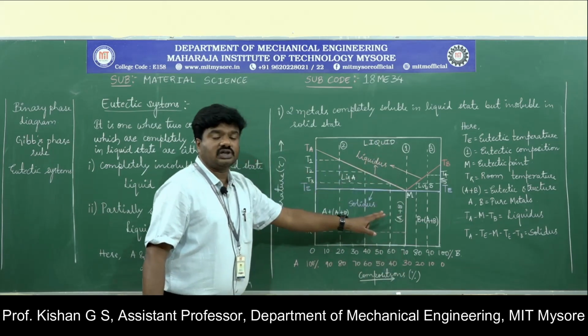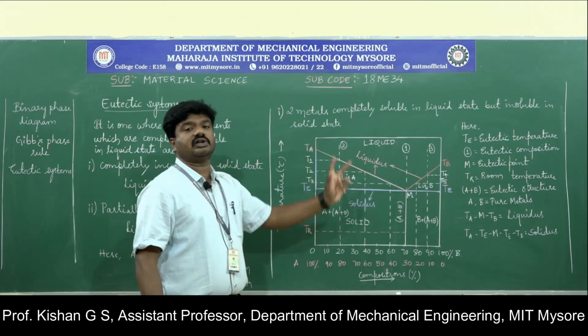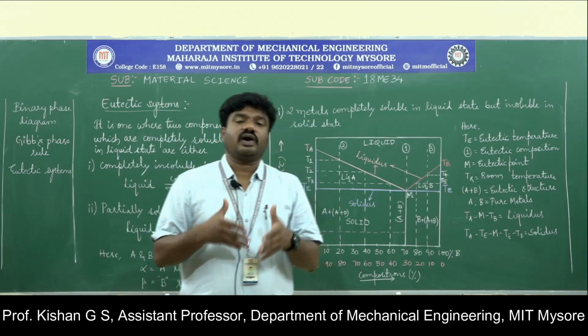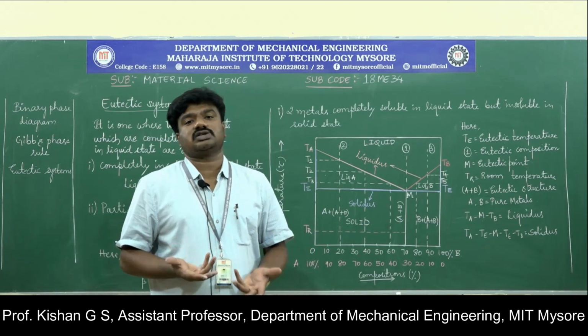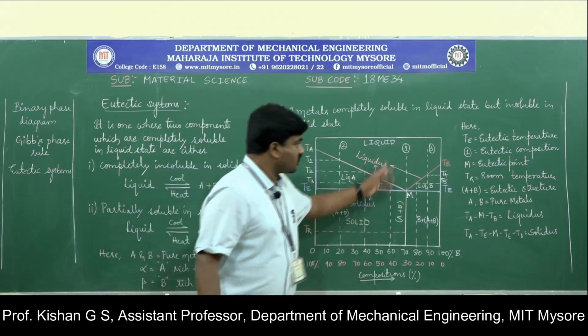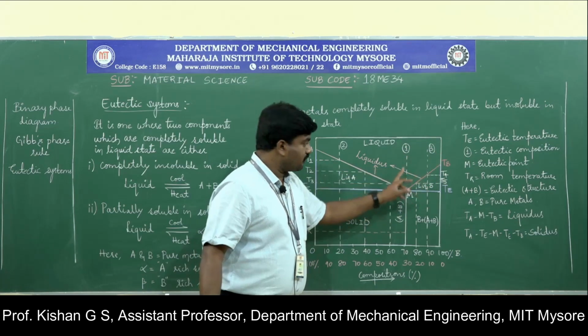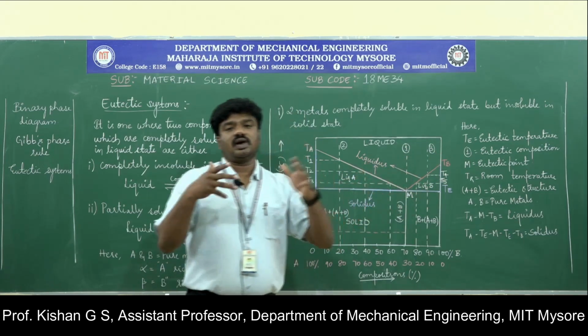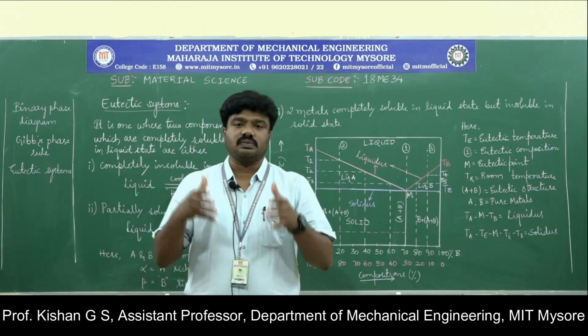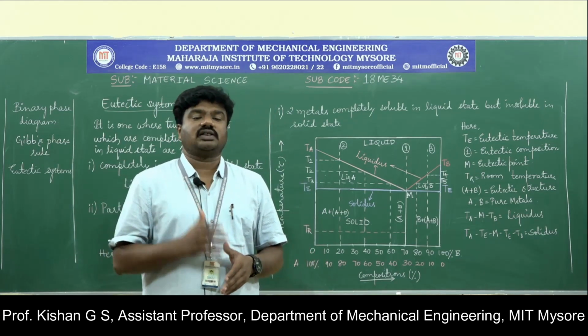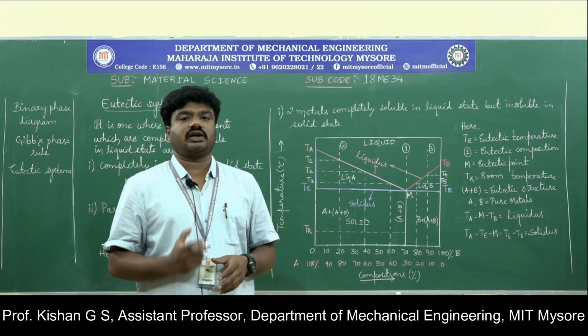That is the combination in which both the pure metals combine together or solidify together while being completely insoluble in the solid state. Hence, that is the composition to be referred to as the eutectic composition, the point at which both the pure metals meet to completely solidify. That particular point is called the eutectic point.